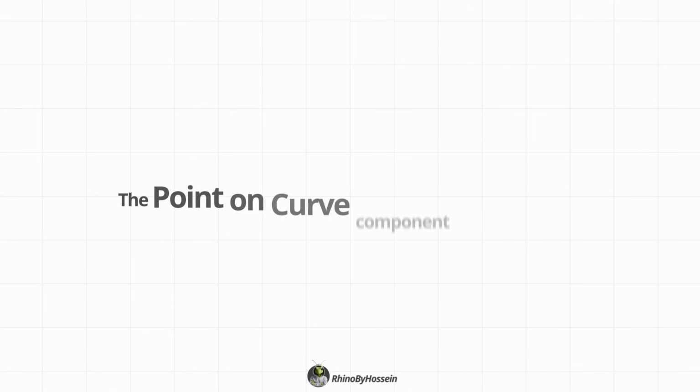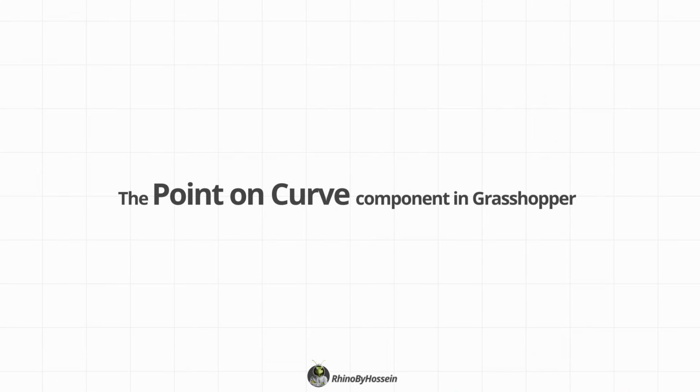The point on curve component in Grasshopper is used to place a precise point on a curve. It works by taking a curve as input, along with a parameter value t, usually between 0 and 1, or based on the curve's length. The component then outputs the point corresponding to that parameter on the curve. This is useful for precisely locating points along a curve, dividing a curve into specific points, or creating relationships between other geometry and the curve. In other words, by changing the t value, you can move the point continuously along the entire length of the curve.